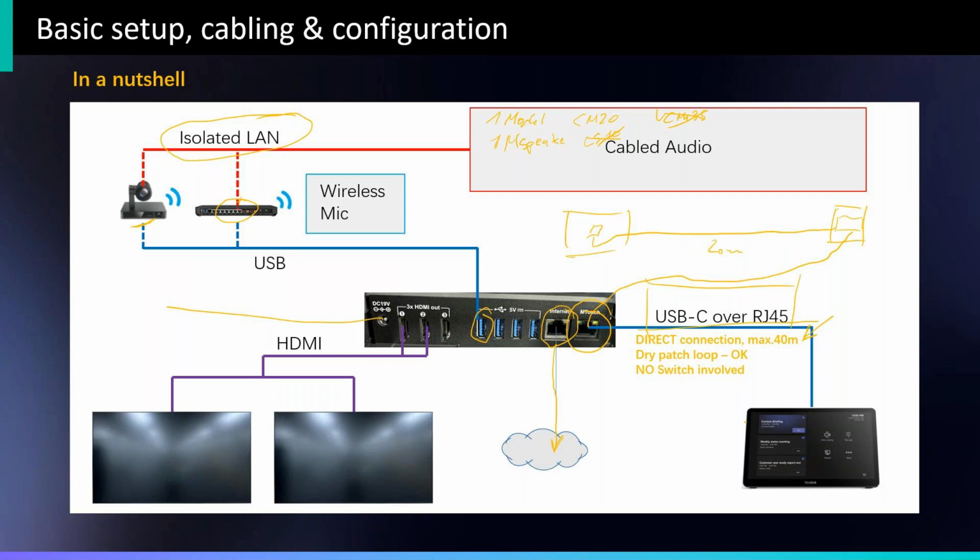And again, that also comes down to the quality of the structured cabling. Cable quality, if there are any tight bends inside, shielded installation cable where the shield is pressed into the wires, or termination that is not properly done, we have signal loss. It all comes down to the actual installation. You can make a dry patch loop in the comms rack.